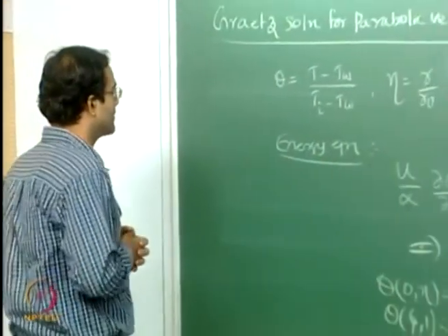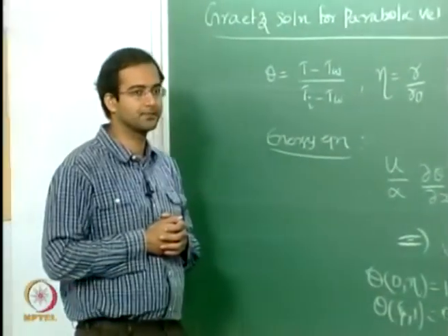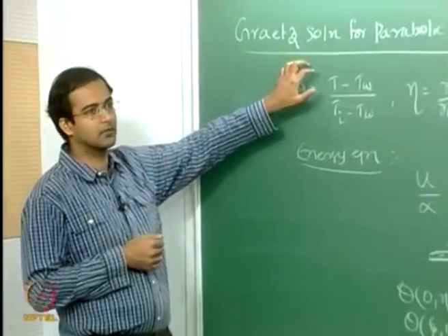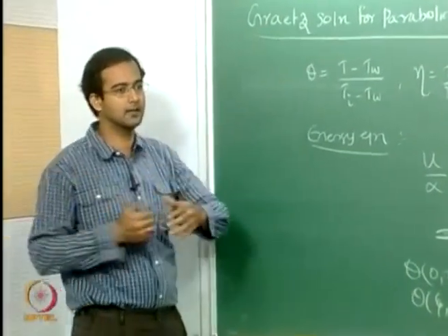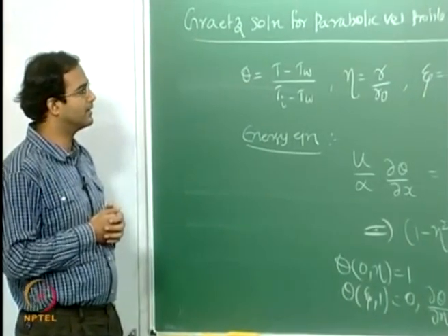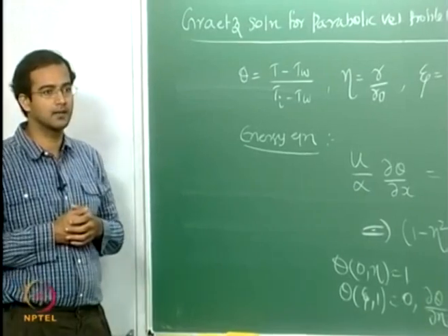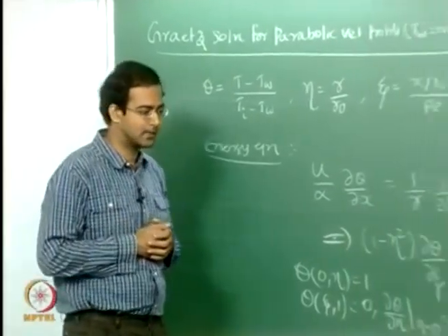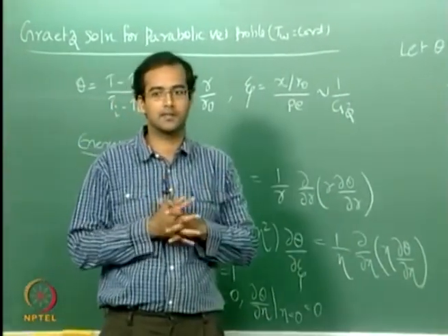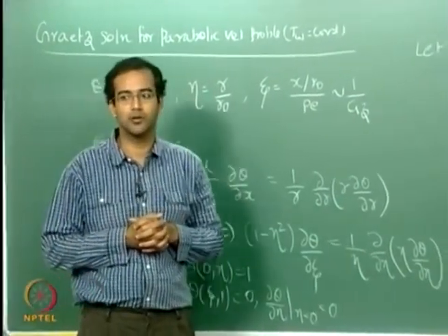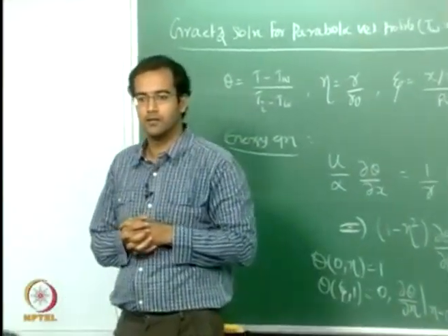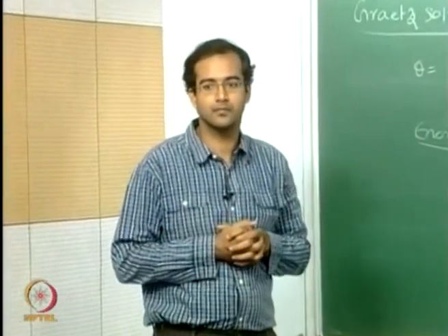That is what we call region 2. So, Graetz assumed a slug flow, which does not vary and is uniform everywhere, and he had developed a solution for constant wall temperature, which we had seen earlier. So, what were the eigenfunctions essentially in the original Graetz problem? The eigenvalue problem there was actually a Bessel equation, right.